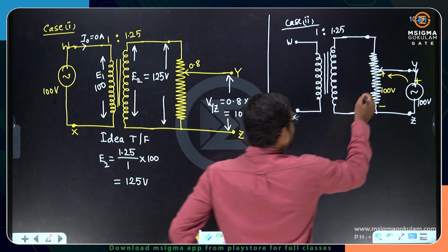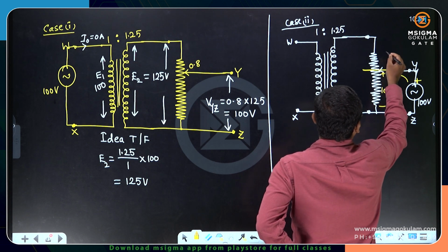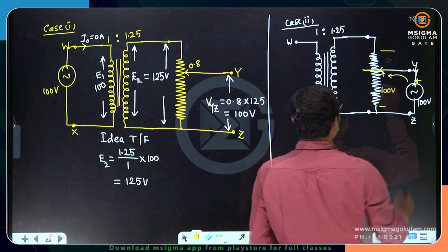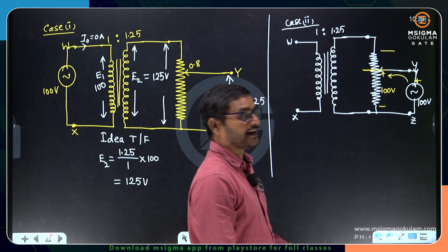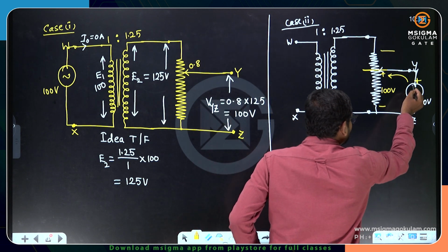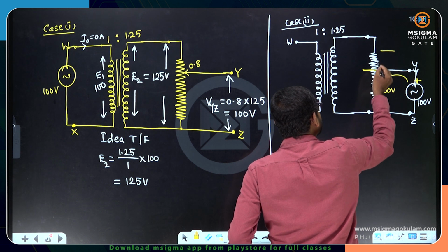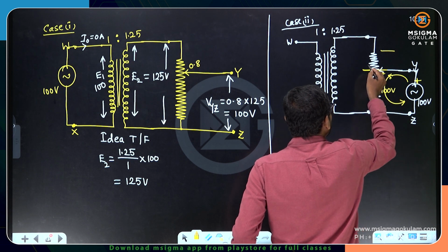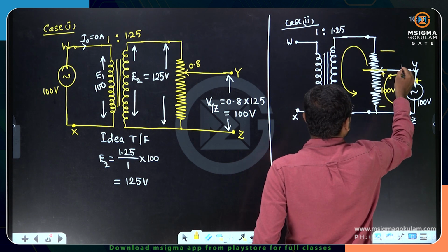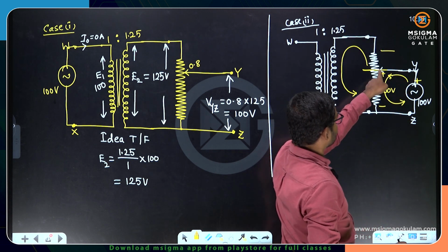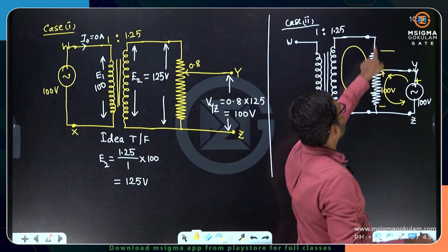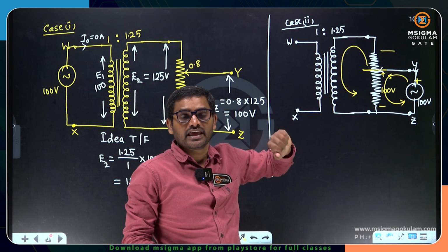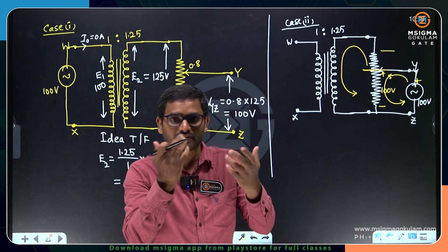Now the remaining 20% portion, you need to find the voltage drop. The current delivered by this voltage source may divide. Some part of the current will circulate here, and some part here. Current enters here and divides through the 80% path and the 20% path. Unfortunately, the transformer is an ideal transformer. If it is ideal, will it draw any current? It will not draw any current.